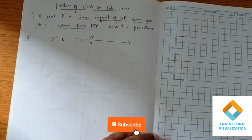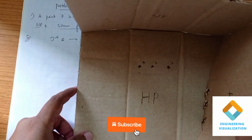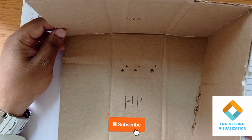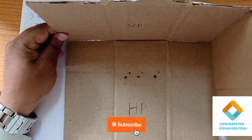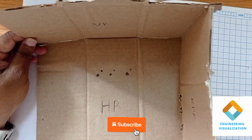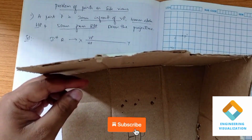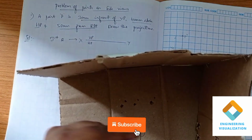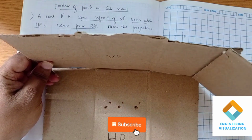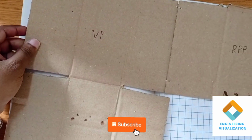This is the side view. So where exactly is it in the quadrant? This is our HP plane, this is the vertical plane, and this is our RPP, the right profile plane. The right profile plane is adjacent to the vertical plane. In this problem, a point P is 30 mm in front of VP, 40 mm above HP and 50 mm from the RPP. So it will be adjacent to the vertical plane. When it is drawn in orthographic, it will be like this.